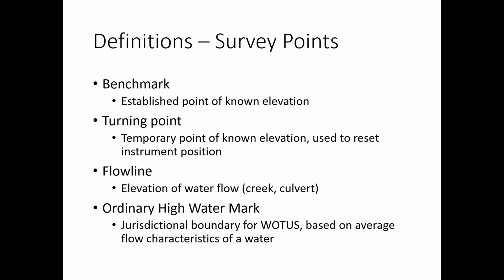So a few more definitions, specifically for when we're actually doing our surveying. A benchmark is generally an established point of known elevation. This is kind of how we start all of our surveys. We don't know where we are in the world unless we reference something that we do know. And so we use a benchmark. Generally, this is a point of known elevation.